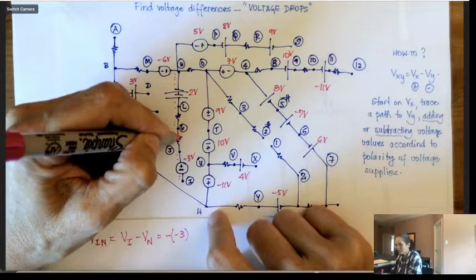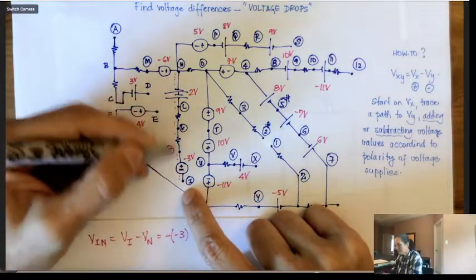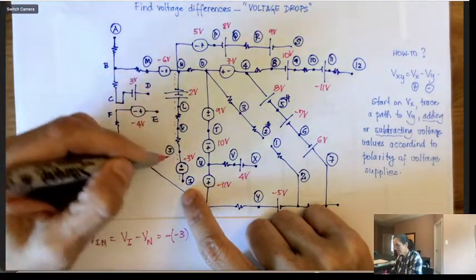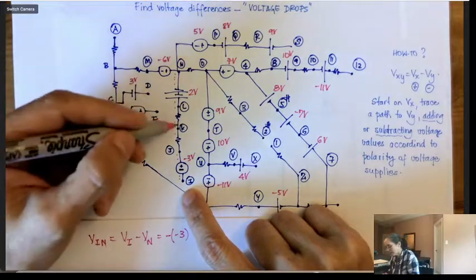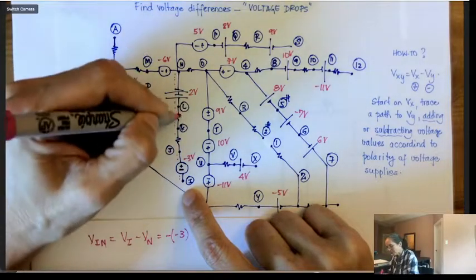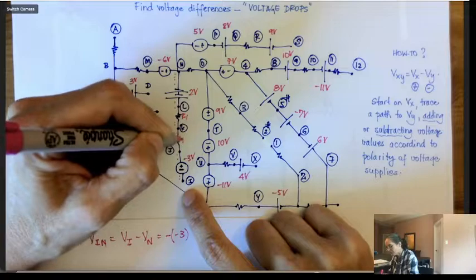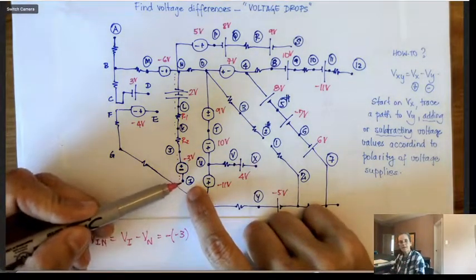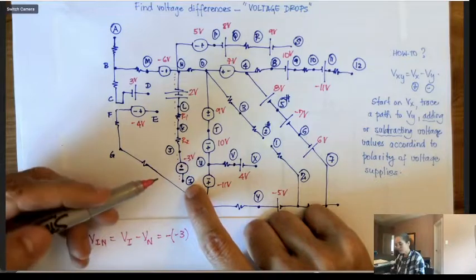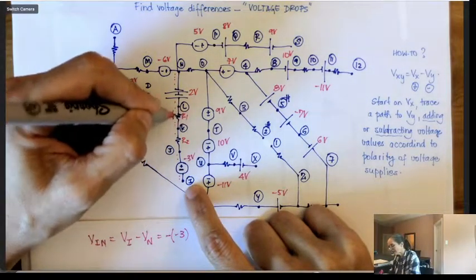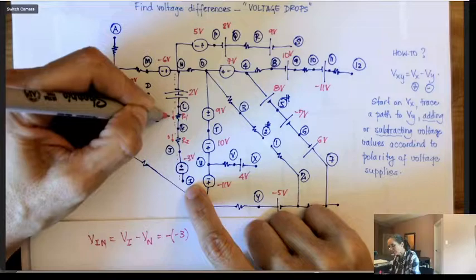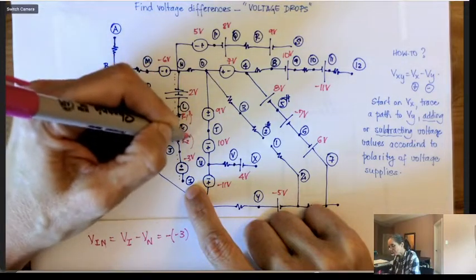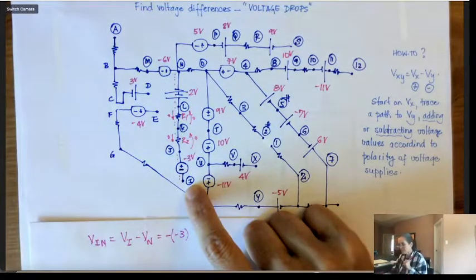Now this resistor here, because it's in the middle of two other resistors, I can even add these two. Let's say if I had R1 and R2, I was going to add the two, but what happens is the I is a node that's not connected to anything else, to no other branch. So I can guarantee that the current here is 0. So I can guarantee that the voltage drops here are 0.